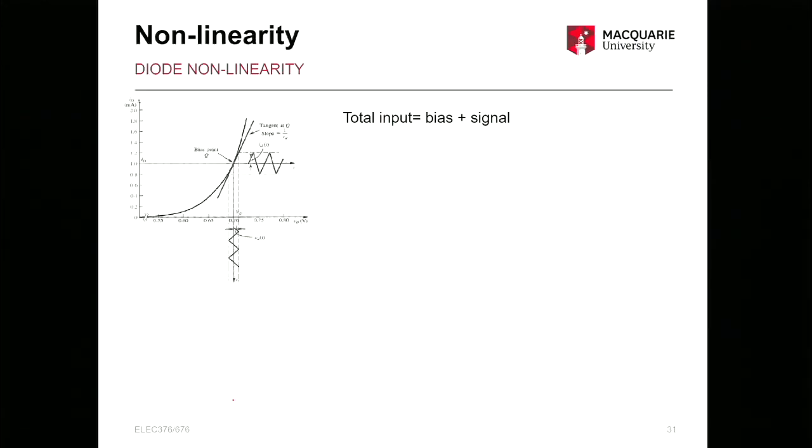Okay, so this is just a recap of what you have done, and this is the last topic of today's lecture. You have checked the nonlinearity, or basically you are looking at the high frequency response of MOSFETs and BJTs. But what you were also looking at was what extra frequency components are generated in the FFT. And you saw that the MOSFET generated 2 major components and BJTs generated many more frequency components, and one was messier than the other. You tried to remove them by adding an RC filter, right? So I hope you still remember all that.